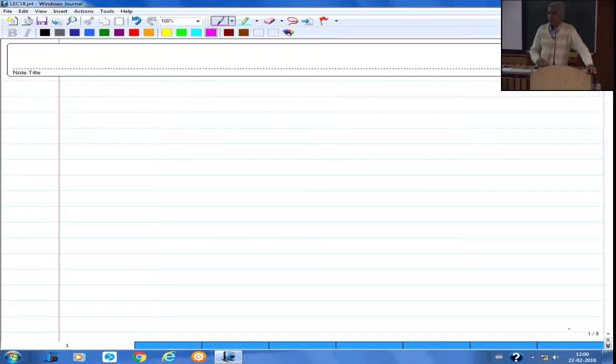Yeah, there is some kind of inconsistency here. What we assumed is the centroidal axis displacement, and then you can get the displacement variation across the thickness from the expression for epsilon zz, as del v by del y is equal to minus nu times epsilon xx. So you can actually get an expression for v which varies along the y direction. But because you still don't get an independent strain epsilon yy, we still go with taking v as a constant throughout the thickness.